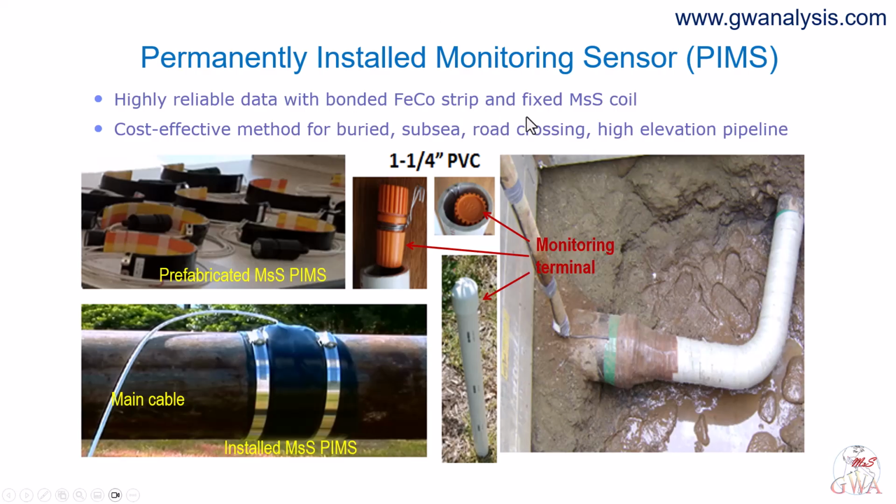Anything rigidly bonded across a large area has to accommodate that movement, and over thousands of cycles, a bond under that kind of strain will eventually fail. By bonding only the thin strip and leaving the coil fixed but separate, the installation has far less exposure to differential expansion, and the coupling stays good far longer.